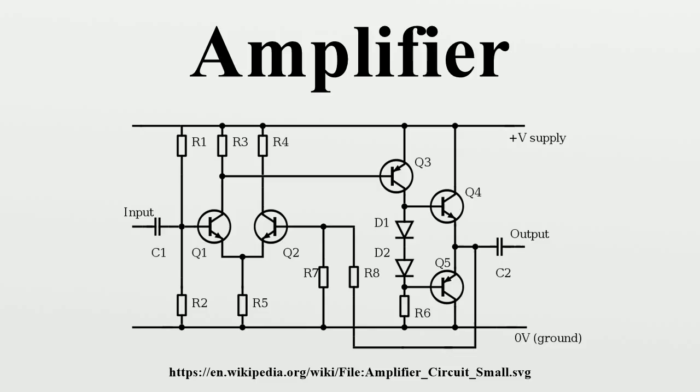Frequency response, not just the frequency range but the requirement that the signal level varies so little across the audible frequency range that the human ear notices no variation. A typical specification for audio amplifiers may be 20 Hz to 20 kHz plus or minus 0.5 decibels. Power output, the power level obtainable with little distortion, to obtain a sufficiently loud sound pressure level from the loudspeakers.